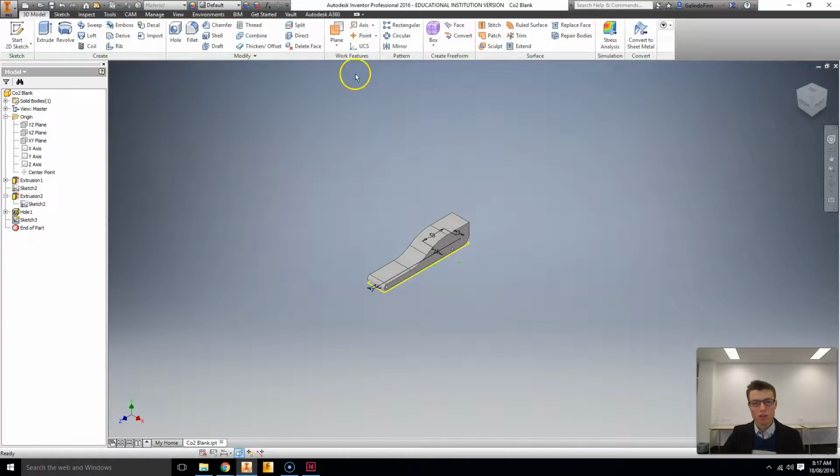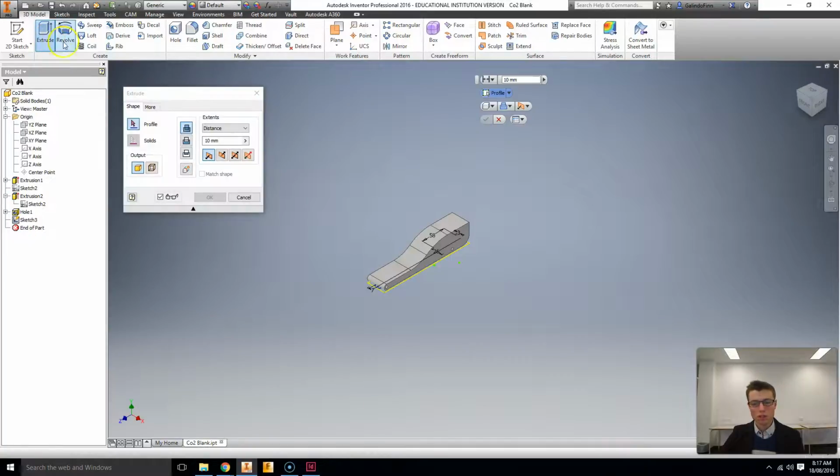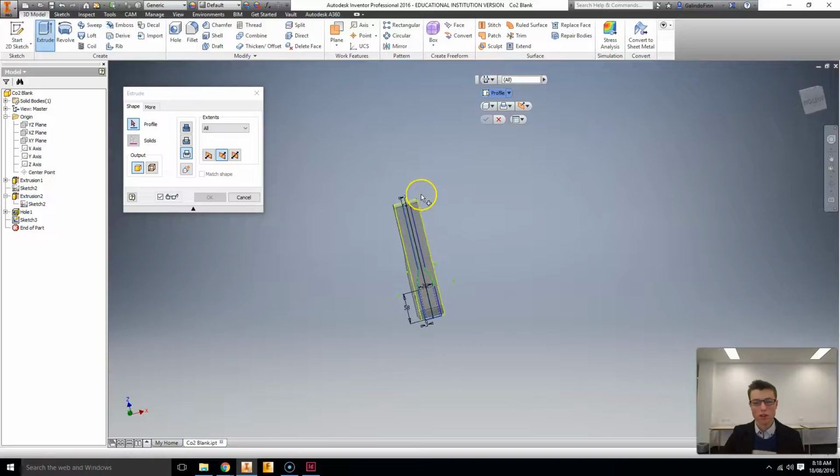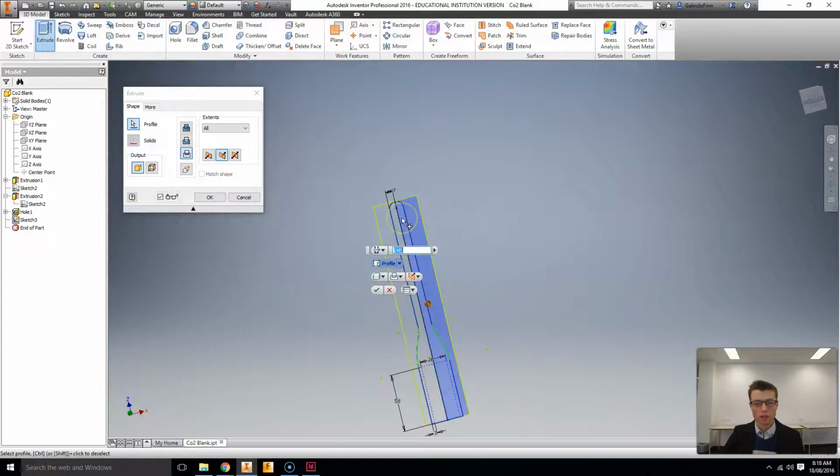Clicking Finish Sketch, I'm going to do the Extrude tool for the second time, or third time now. I'm going to select Intersect, and I'm going to go through all. And this bit only works when you select the profile. You notice it's an orange button here, so select. I need to click on the profile I want to use. I'm going to zoom in and select the two inside halves.